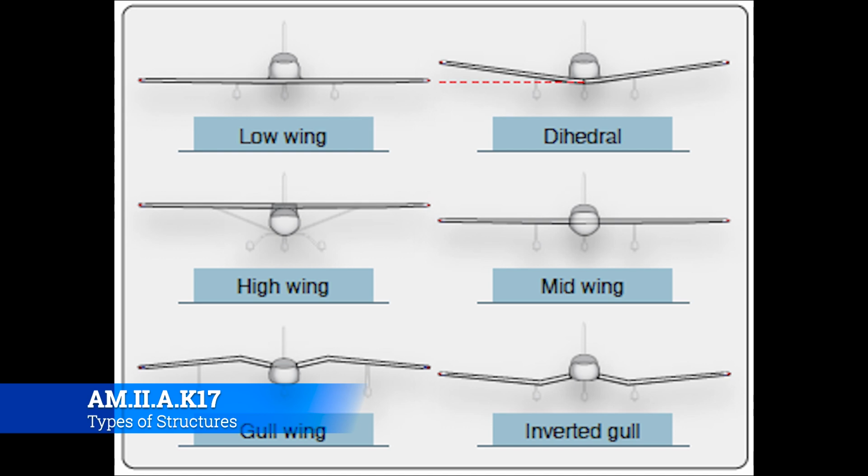High wing aircraft allow you to look down. They also allow the aircraft to fly slower, because it takes less substructure to attach the wing and all that good stuff. So it's just a more efficient wing, and a lot of your trainers will be that way.